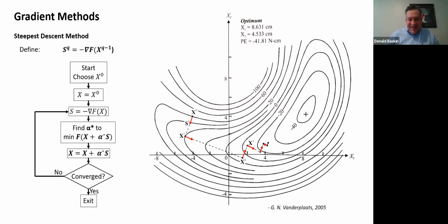I'm sorry. Anyway, just remember, fundamentally, x1 and x2 are design variables. They might be the diameter of a tube. They might be the wall thickness. They might be the length of a square tube. When you're talking about structural optimization, they are just geometrical features of a structural member. It could be a head tube. It could be a fork blade. It could be a brake caliper arm.